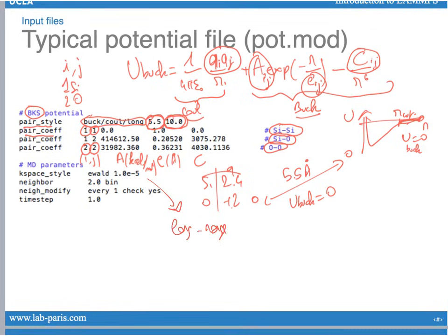We will come back to this in a subsequent video. We need to specify the method that we are using for this, which in this case is the ewald function. We need to specify here a convergence criterion. I'm not going to go into details of this, but this is for the Coulombic interaction, and in this case it depends on each system. This line should not be changed.